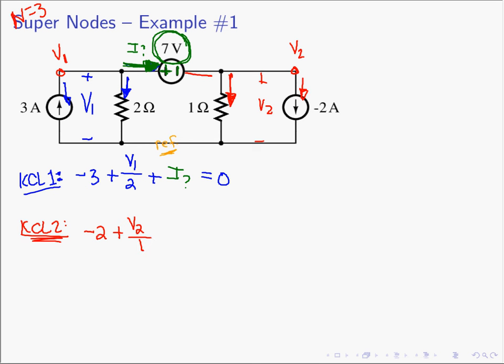And then we're looking for the current going off to the left. Again, we're back to a voltage source. What's the current through a voltage source? We don't know. There is no relationship between the voltage source's voltage and its current. The current that flows through this voltage source will be whatever makes the rest of the circuit happy, that is, satisfies KCL, KVL, and Ohm's law. So this red current going to the left is obviously in the opposite direction from the I question mark we found earlier.